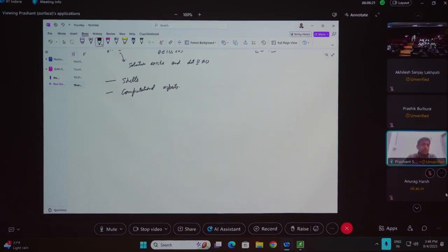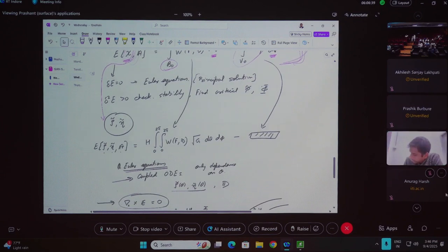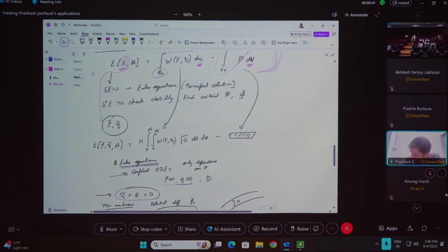and as I said, the key assumption in the membrane theory was that membranes do not have any bending stiffness. And when I was writing down the energy functional for a membrane, the key assumption comes in here, that when you write down the elastic energy in this integral, which we had yesterday, the thickness just comes outside directly. And we can see how we reformulate things for a shell problem.